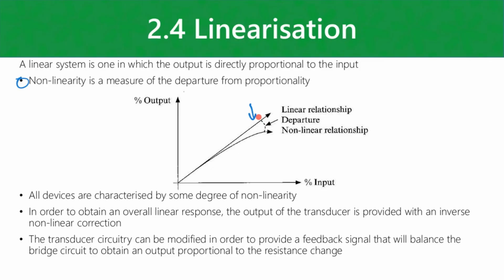You can only put so much magnetism in an object, right? So you get to a point where you can increase the flux, but the flux density in the material doesn't increase any further, and you don't have any further increases in voltages or currents relating to that. Right, so that would be an example of nonlinearity.